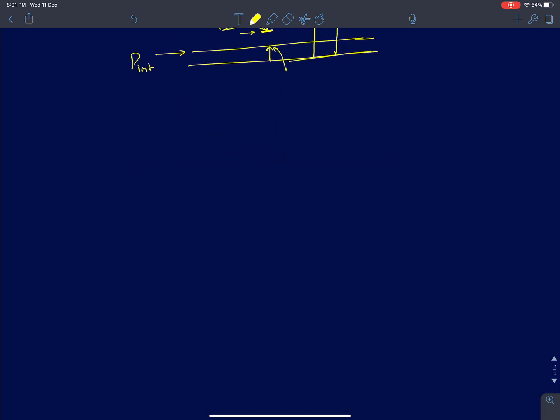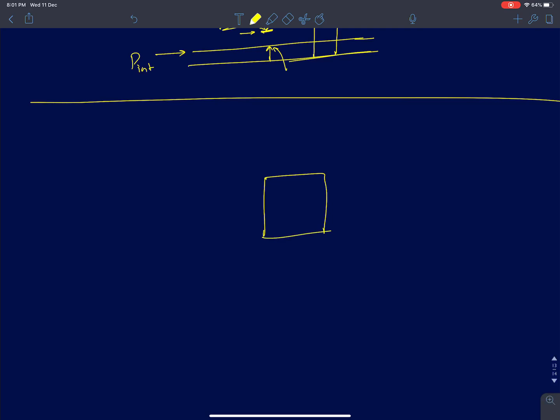Okay, the other more important thing, which I very briefly mentioned in one of the lectures itself, is losses. I mean the loss of a band pass filter. Whenever we insert a band pass filter after, say for example, an antenna, before it goes to an LNA, we discussed that we need this band pass filter for two purposes.